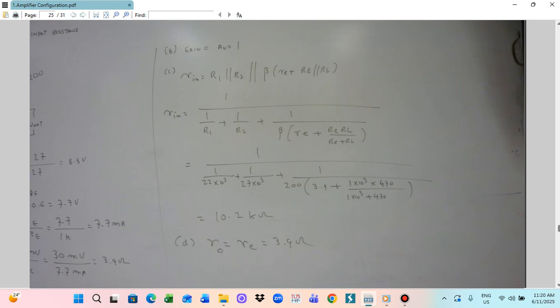So moving on from the amplifier solution, the next topic will be the application. The CC amplifier is not really utilized for amplification, because for an amplifier we have to provide gain. You see here this CC amplifier gain is unity. Unity means the input and output signal are the same. Input is 1 volt, output also 1 volt.